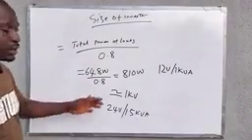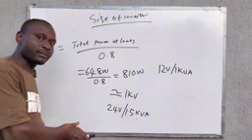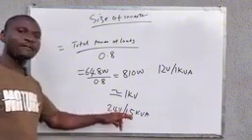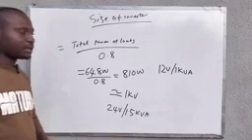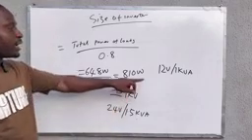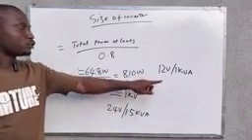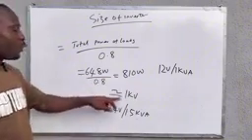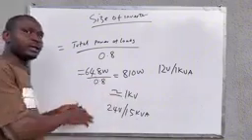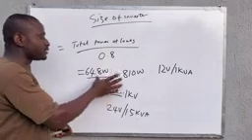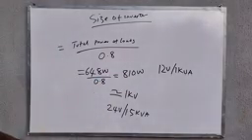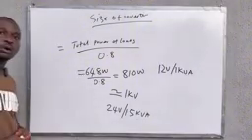Now, for the 24 volt system from our battery bank, we are going to use a 24 volts 1.5 kVA inverter. Why? It is difficult to get an inverter that is rated 24 volts 1 kVA. But if you have the inverter, it will still work very well here because the size of inverter that will power this load is 810 watts. So this is how to size a solar power system for your home.